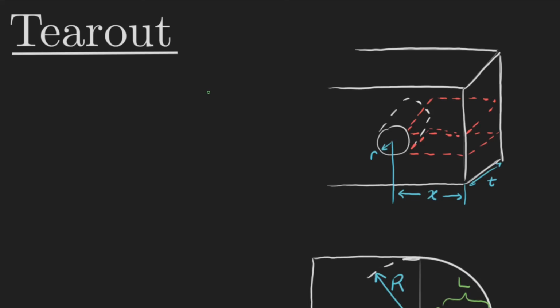Now for the shear failure, we're going to have something called tear out. And the idea here is that if you imagine we have our beam right here, this is a rectangular beam, and then it has a slot right here, which is where a pin is coming in, and this pin is basically exerting a force in this direction. If it turns out that these areas right here, so this area above it going out to the edge, and this area below it going out to the edge, if both of these can fail in shear, then what can happen is this entire little chunk of it can just pop out, and basically then it's broken out, right? The pin no longer works because there's just a gaping hole in our assembly.